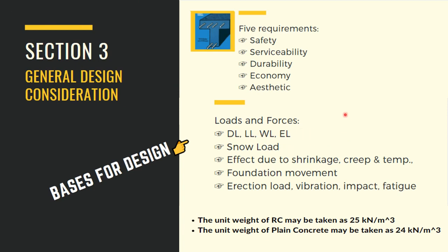The design load is the load that should be taken for design of any structural member. If we give the load for design purposes, then that load can be called a design load. In case of the working stress method, it is the characteristic load. We have to say that load as characteristic load, but not the design load as in limit state, because a partial factor of safety is multiplied for limit state design, but in case of the working stress method we are using a factor of safety, not the partial safety factor as in the case of the limit state method.